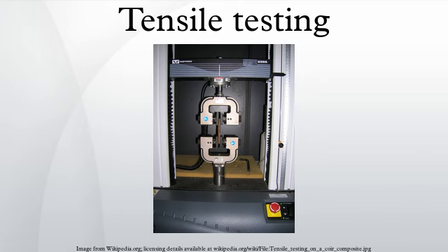In large castings and forgings it is common to add extra material, which is designed to be removed from the casting so that test specimens can be made from it. These specimens may not be exact representation of the whole workpiece because the grain structure may be different throughout. In smaller workpieces or when critical parts of the casting must be tested, a workpiece may be sacrificed to make the test specimens. For workpieces that are machined from bar stock, the test specimen can be made from the same piece as the bar stock.